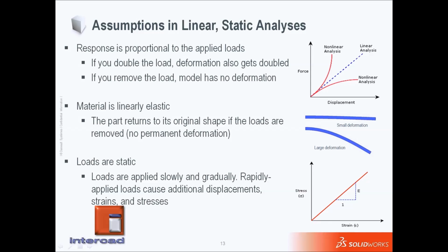So three major things we covered here: linear analysis, where we have proportional rates of force and displacement; linear material, where the material gets back to the original position if we remove the load; and the third is how fast or how slow we apply the load.